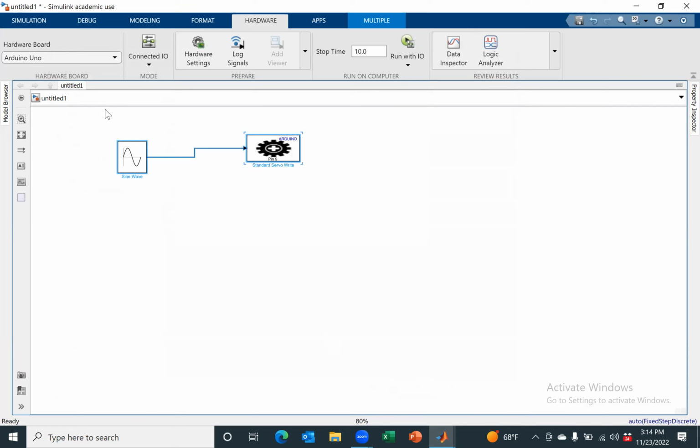That way you have the image that is captured inside MATLAB. You analyze the image, then get the relevant data from the image, and then program your microcontroller to send a pulse width signal to the servos, and then your robot can go to that position. So this is how a simple image-based acquisition works.